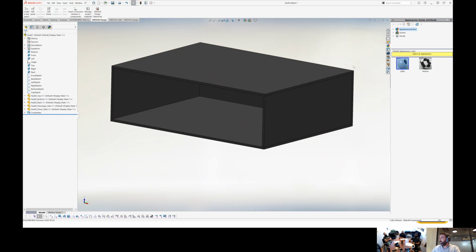Okay, so now we want to complete that. So for that, we are going to, for example, create the connection between our different panels with parametric rules and hardware insertion. So I have created for you different rules. So we have a screw rule for the connection, and we'll see we have also some drilling pattern for the front iron we will insert after that. And the screw dado is already used in the drawer.